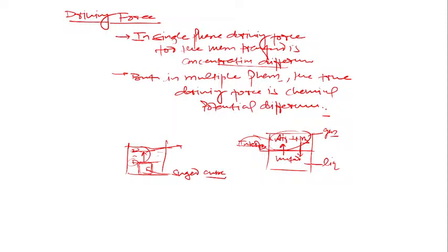You know the molecules are very random in nature, so some molecules will get transferred into the water and some ammonia from the water will also get transferred into the gas phase, but the net transport of ammonia is from the gas phase to the liquid phase. Net means, suppose 10 moles of ammonia enter the water, then 2 moles of ammonia get out of the water because of its nature. So ultimately the net 8 moles will get absorbed into the water. Yes or no?